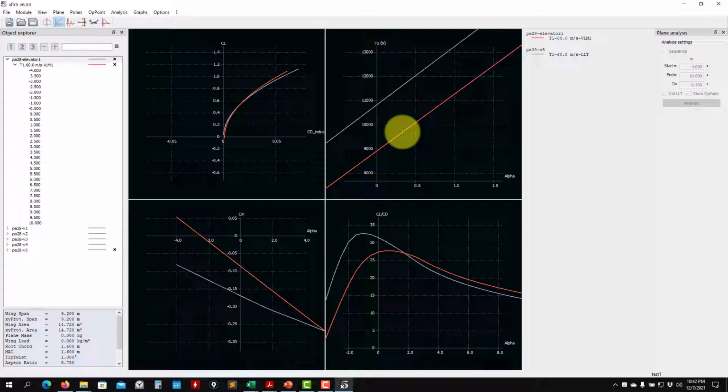Always when designing, choosing your airfoil, designing the wing, pay attention to the moment, because the moment can destroy your designs. If you have a wing that produces too much moment, then it will be too difficult to balance, or not too difficult.